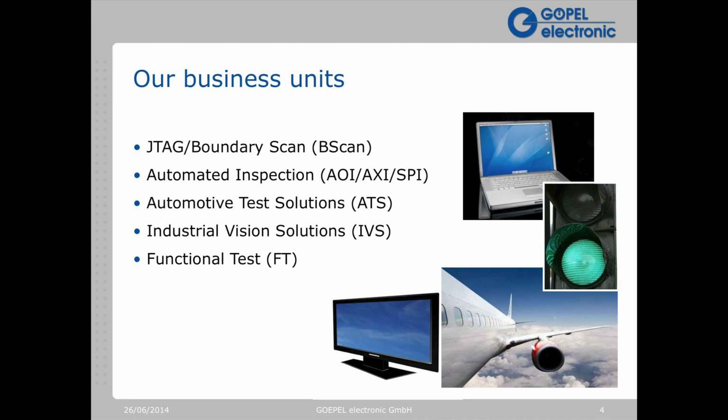We not only support the traditional boundary scan applications of connectivity, but we also develop tools that are very focused on extended boundary scan capabilities, such as embedded test, where we can use boundary scan access to access onboard microprocessors or microcontrollers or FPGAs, and use those onboard components as embedded test capabilities. So this greatly enhances the capability of JTAG boundary scan applications and pushes these technologies into a new realm, and we're the market leader in that capability.